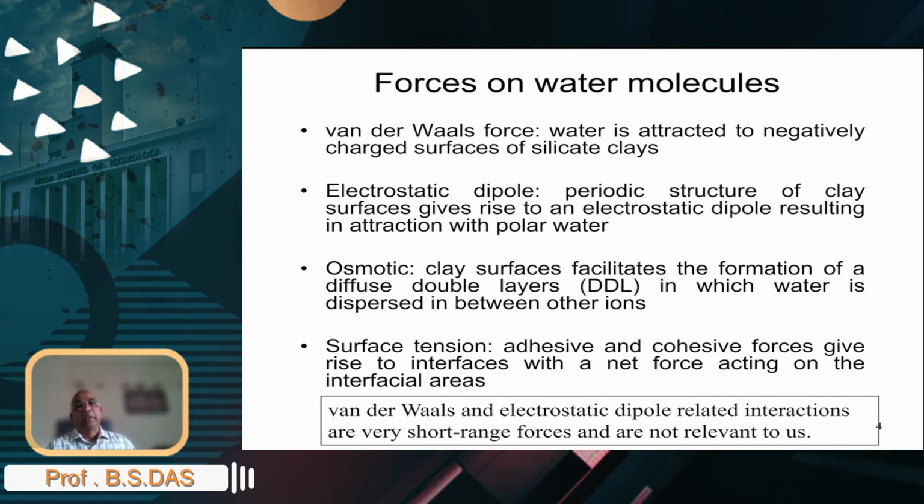As you know, water is a dipolar molecule, and so the positive and negative poles of the water would be orienting in a fashion that gives rise to van der Waals force between them. You also would imagine an electrostatic dipole, and that's because of the periodic structure of the soil clays. As you remember, clays are layered structures.